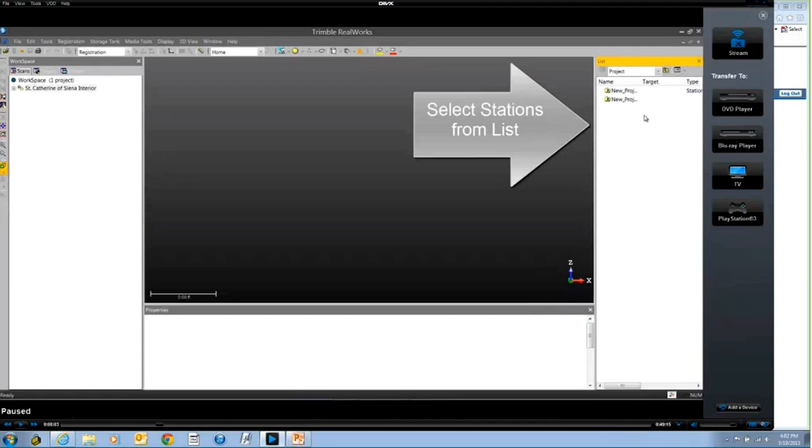So the workflow I've used is I've opened the project from the SD card from the TX5 in Scene. I've applied the color in there and saved the project, which then moves all of the colorized FLS files into one folder called Revisions. Then from RealWorks, I'll go in and open a project. I'll browse to the folder where those FLS files are stored, select all of those, and then they'll come in and be converted to TZF files, which is the native RealWorks file format.